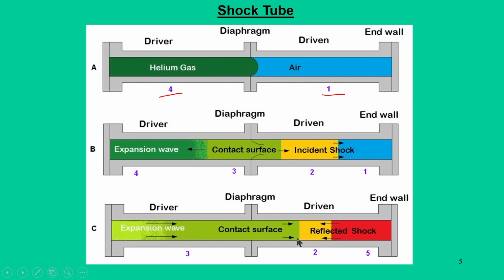So, basically, when such a thing happens, we can say that the test flow is terminated. That is because whatever the test gas was, air, when the contact surface and reflected shock meet each other, it means that the test gas gets diluted with the driver gas. So, we say test time is over. That is the time duration available to us to perform the experiments.